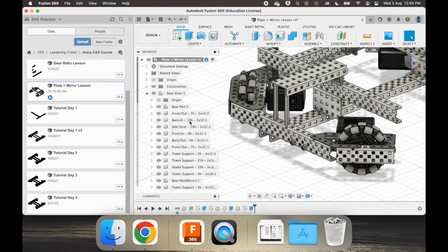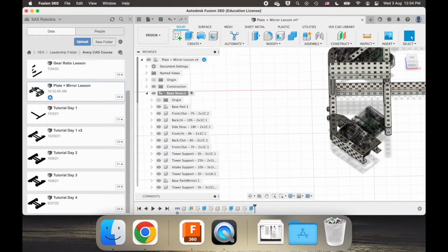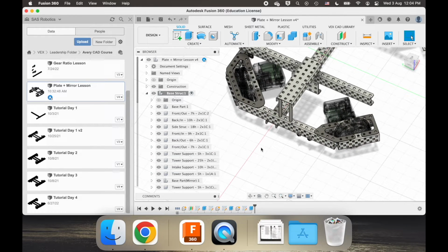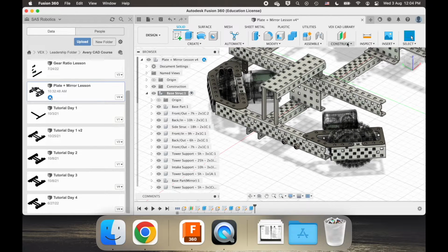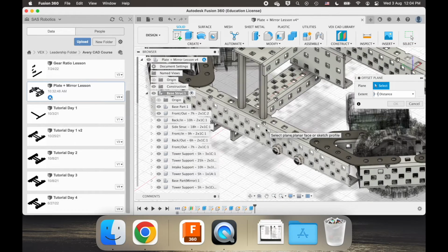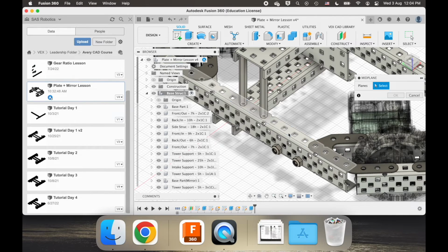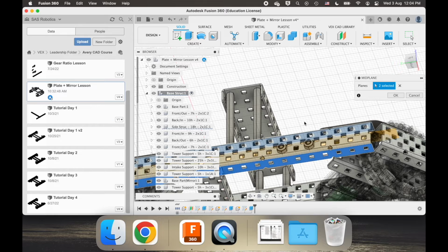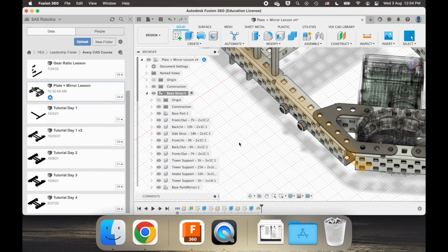Now, I'm going to activate base structure probably. Like in the sketch mode, where we had to create a line to mirror across, when you're working with these 3D components, you have to create a construction plane to mirror across. So if I go to construct, offset plane, actually, there are different kinds of planes we can make. I'm going to make a mid plane, just to make sure this is right in the middle between these 2 planes. And now we have a mid plane here.